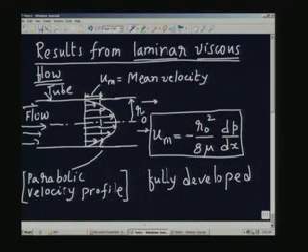So, the velocity profile is totally unchanged as the fluid progresses along the length of the tube. As the flow takes place from left to right, the flow velocity variation with respect to the radius, in the radial direction, remains the same, and this velocity profile is given by what is called a parabolic velocity profile, which is indicated by the parabola here. The velocity is 0 at the walls and a maximum at the center line or the axis of the tube.